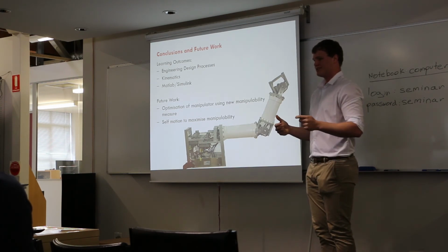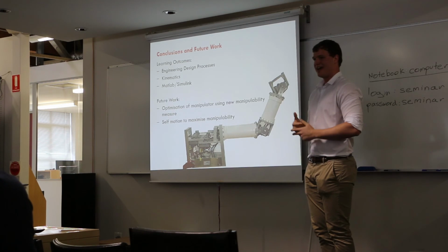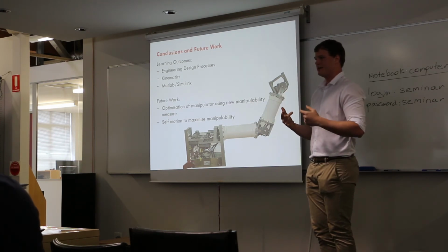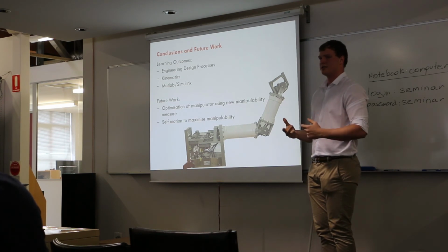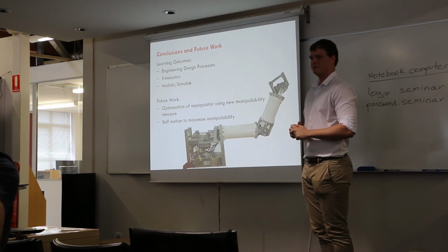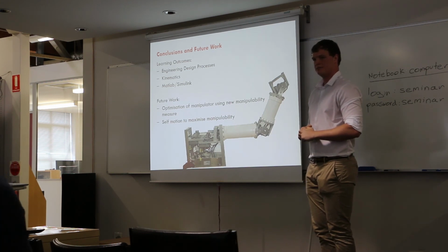So the way I get around that is using the tip following, where you don't have to have these predefined obstacles. You can just say where you want the end effector to go, and assuming there's not too much error, you can assume that the rest of the arm isn't going to collide with any of the obstacles. Yeah. One last question.